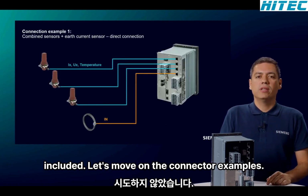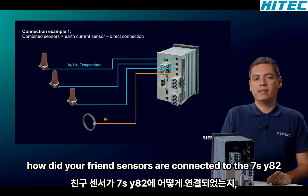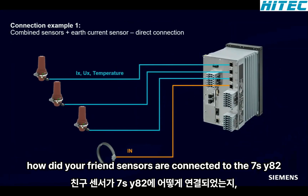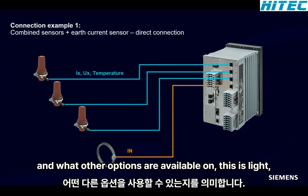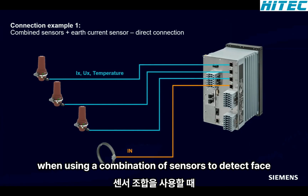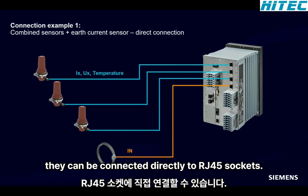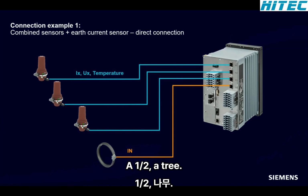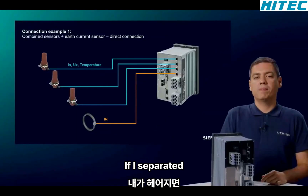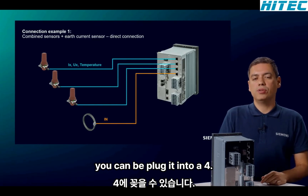Let's move on to the connection examples. That means how the different sensors are connected to the 7SY82 and what other options are available. On this slide, we see the simplest solution. When using combination sensors to detect phase current and conductor to earth voltage, they can be connected directly to RJ45 sockets A1 to A3. If a separate sensor is used to detect the earth current, it can be plugged into A4.